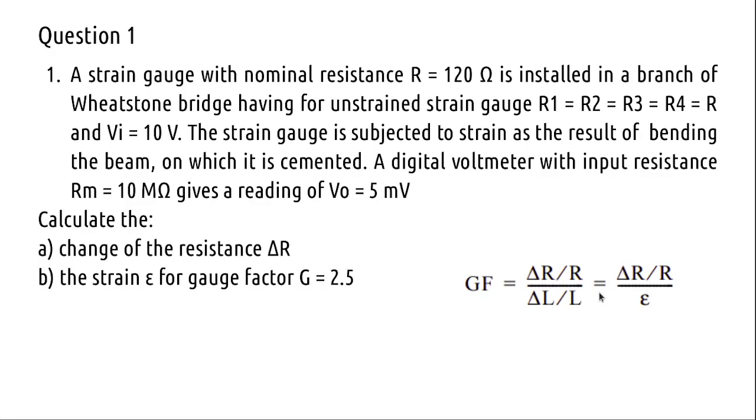What should be the ideal voltage source? What are the characteristics of an ideal voltage source? Say if the input resistance of this voltmeter is low, you are going to draw current. Yes, it will load, right?